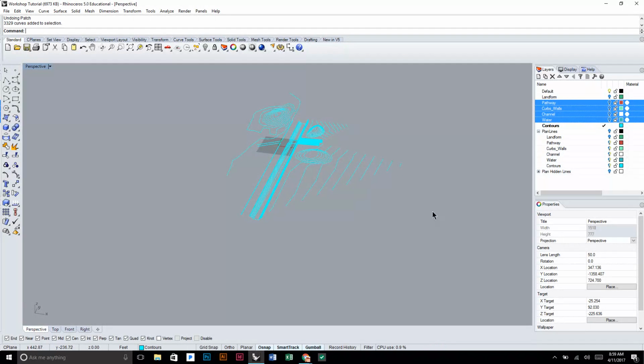Rhino can bring in a lot of different file types, and if you export it as a CAD file, I'm going to assume that metadata is going to be there and Rhino will be able to register that. It's when you do it from something like Illustrator, where it's working on a flat plane, that it won't have those Z values. But what you just did is create it from a 2D drawing anyway, so it didn't necessarily matter.